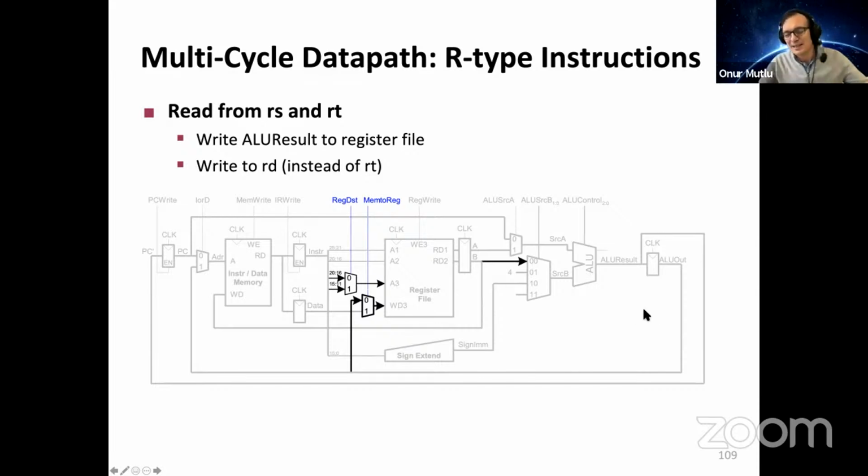So that if you are really hardware constrained, you can do what you suggest, basically. You can have a single read port to the register file and read different registers across multiple cycles. But usually that increases the number of clock cycles that you need to execute R-type operations, for example. That's essentially why this design choice is made. But absolutely, a single read port could be another design choice to make. And that can be enabled, again, by a multi-cycle microarchitecture. Very good. Okay, so this R-type.